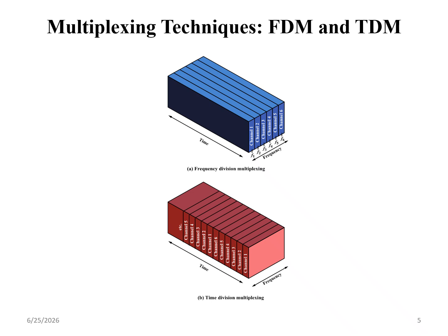Now we are going to discuss time division multiplexing. Here we are not going to consider frequency, because we are looking at time division multiplexing. For each and every time slot, we have channel 1, channel 2, channel 3, channel 4, channel 5. In that way it goes T1 channel 1, T2 channel 2, T3 channel 3, because it is time division multiplexing.